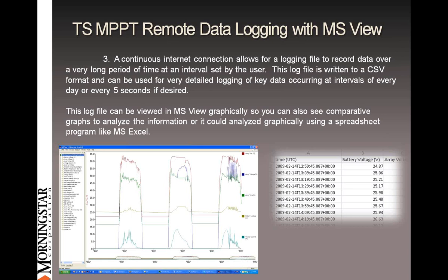And that can have a benefit as well if you want to maybe track one solid day. You can see here where we went into a lot of detail just on one day. This is 3 days total. This middle day, you can see the battery voltage taper off. You can see the charge current drop. You can see voltage, open circuit, VMP, lots of good stuff.